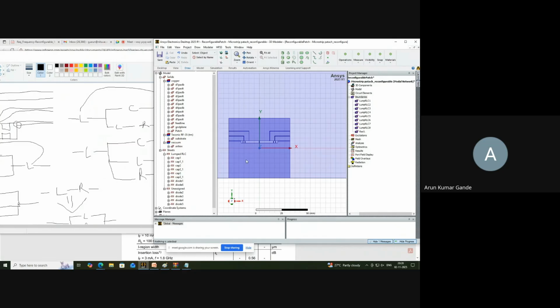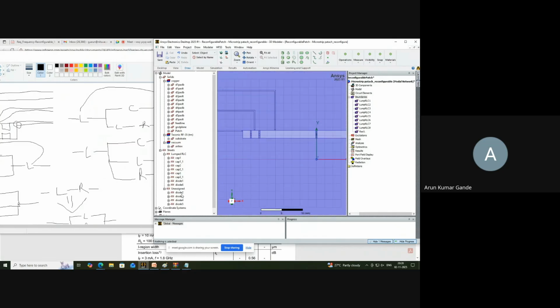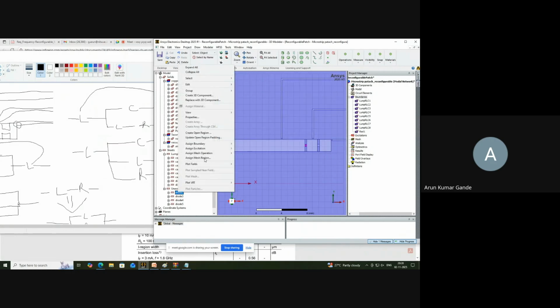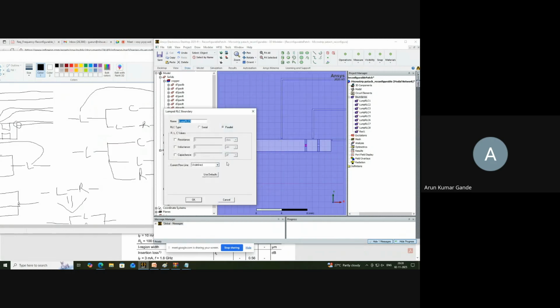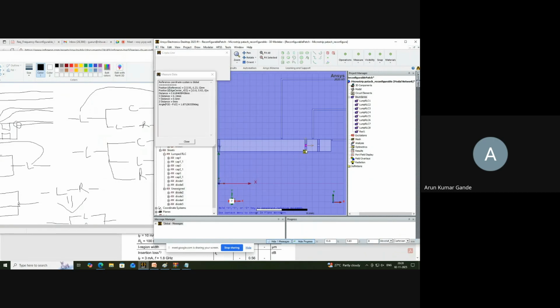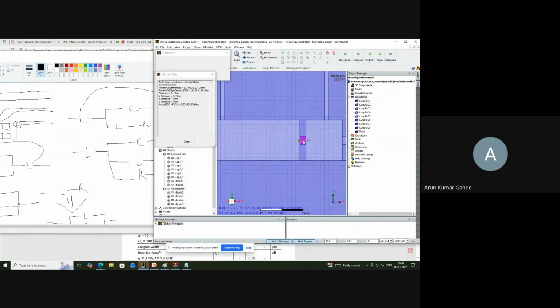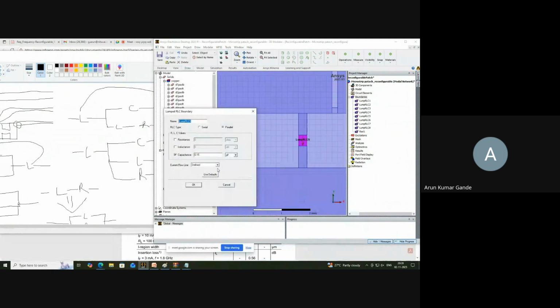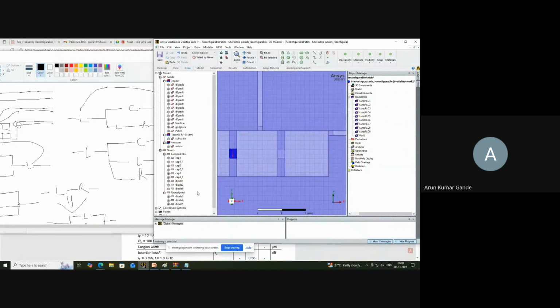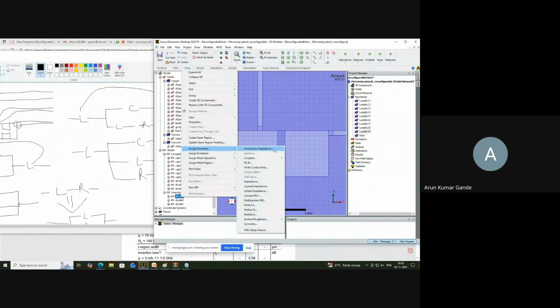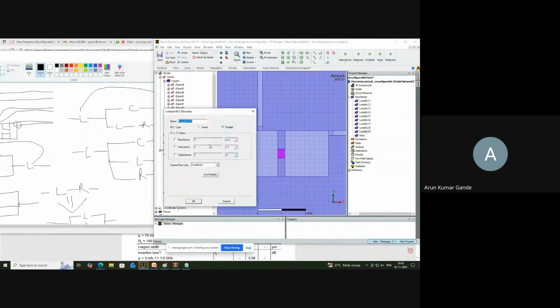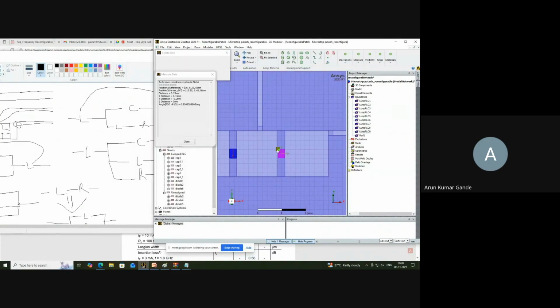And if I'm not concerned much about my parasitics, then I'll select my diode, and if I'm assuming it is in off condition, I'll go to RLC boundary condition. This capacitance is 0.5 picofarad. I'll select this, and then I'll put the arrow from top to bottom, right? And then I'll select my other diode. Here also I'm considering the diode to be in off condition. I'll select this 0.15 picofarad. I'll define the line from top to bottom,